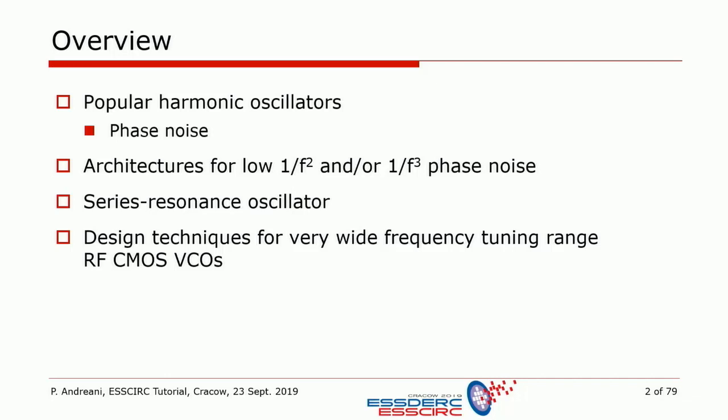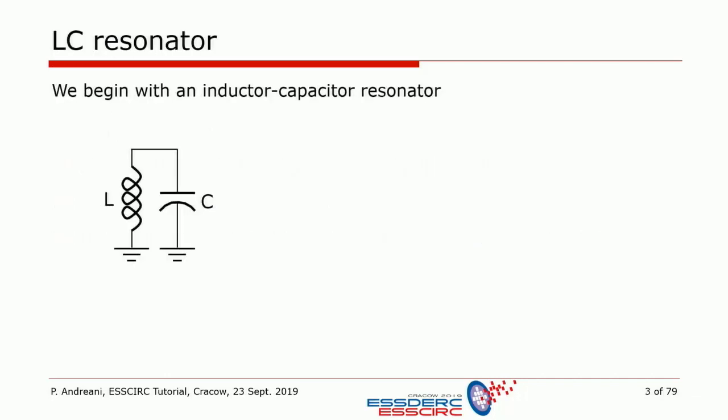So, almost invariably, the harmonic oscillator is set up around a so-called LC tank because it acts as a reservoir of energy, and the inductance and the capacitance that make the tank are connected almost always in a parallel fashion, and in this case the resonance frequency is exactly equal to 1/√(LC), the angular, of course, omega 0.